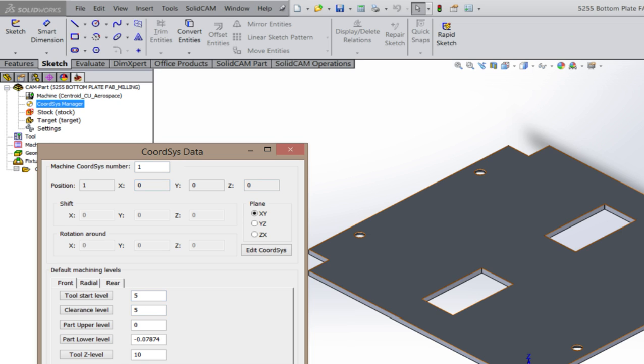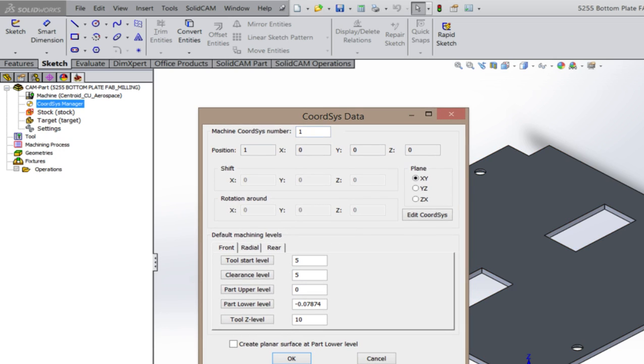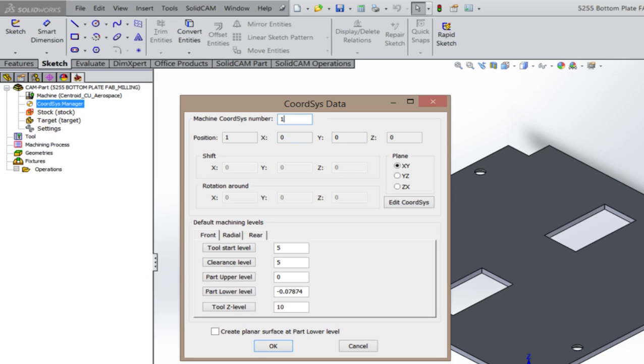I kind of don't want to jump around here, so I'm going to finish as if we were finishing yesterday, and then I'm going to go into more detail here. I've gone into the coordinate system manager. Things I want you to notice is machine coordinate system is 1. I'll be talking about that later. It's critically important, especially for you guys, because you have multiple pieces on each machine. Vail has 3, copper has 2. So it's important here. All right, let's say I was happy with that.